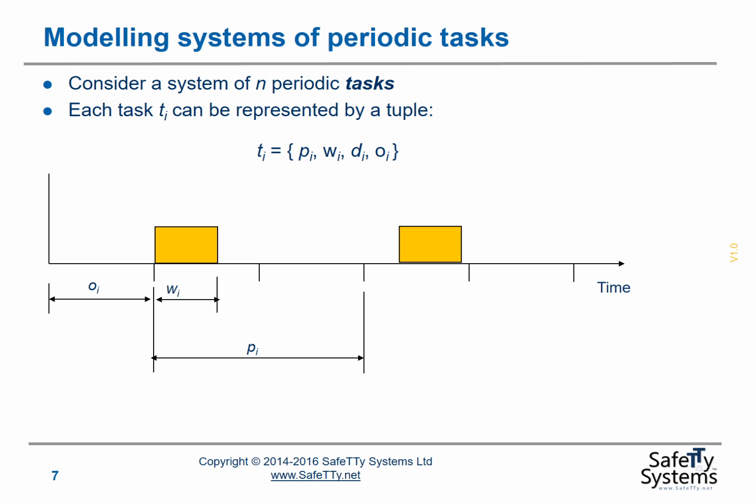The period is 2 ticks, as we've seen. We're saying this is the worst case execution time. And we're saying that the task must complete just before the period, just before it's due to run again, according to this representation.